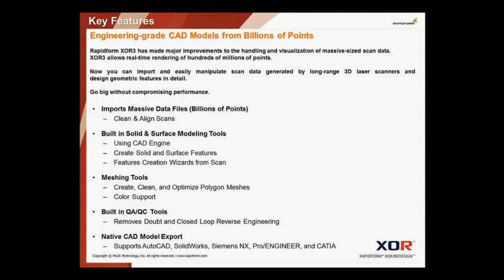And we use real-time rendering. We use some shaders, and we use some dynamic view. That means we reduce the number of displayed points. If you have a huge scan data which you cannot handle very fluently, then we reduce the number of visible points which you don't need. So you can still see the model, but you can move it quite fast.